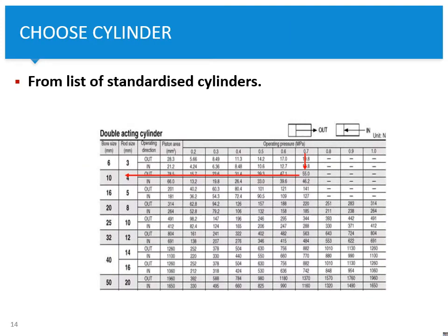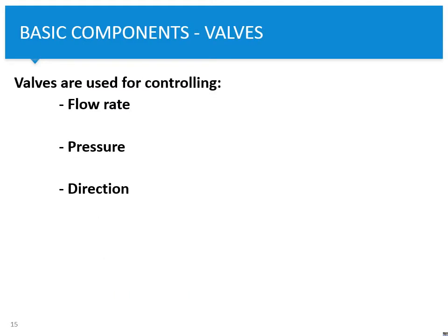So, if you choose a cylinder, you can usually do this from a table from whatever manufacturer you like, while keeping in mind the methods to determine the cylinder size. You can see the size of the bore at the rod side and at the head side. And of course, choose the pressure of the compressor or hydraulic pump or whatever.